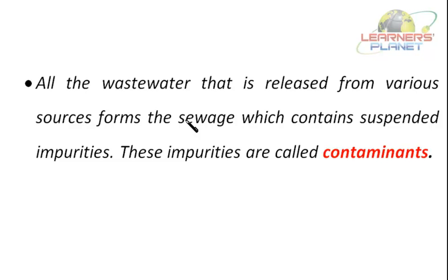So students, there are typical industries too which produce significant volumes of wastewaters, which include fiber plants, paper, steel mills, refining and petrochemical operations, then fertilizer plants. So there are many such industrial plants whose discharges may consist of very strong organic wastewaters with a high oxygen demand that contain undesirable chemicals which can damage sewers and other structures too. So a very fine and highly designed sewer system should be built for such industrial plants.